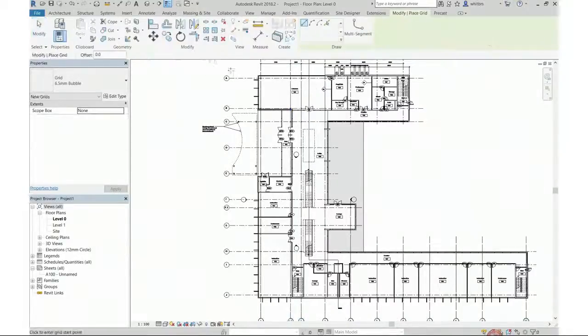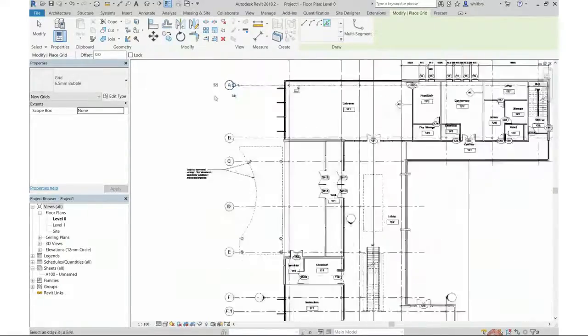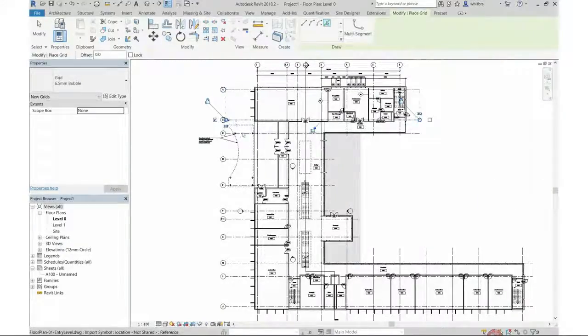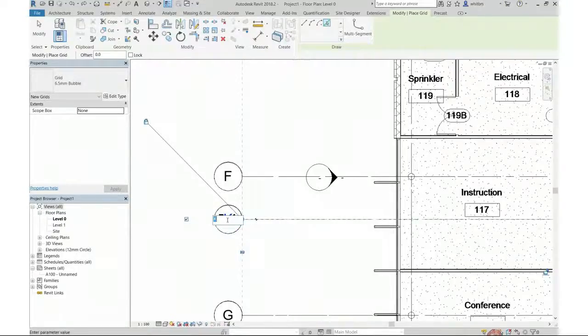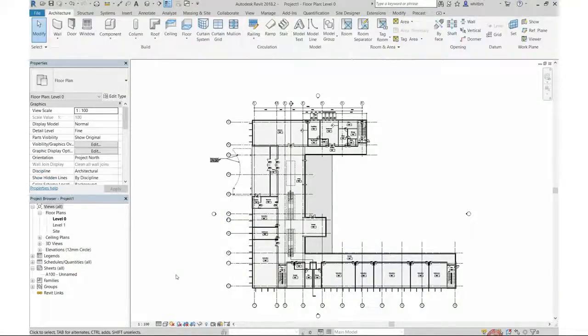So he wanted to have a building in the background that he could coordinate with. He could pick up the fact that some of the stairwells weren't correct when you overlay the DWGs, but he wanted to have a coordinated model. So he was using this linked file as an architectural model, but it's not, it's a wireframe model.